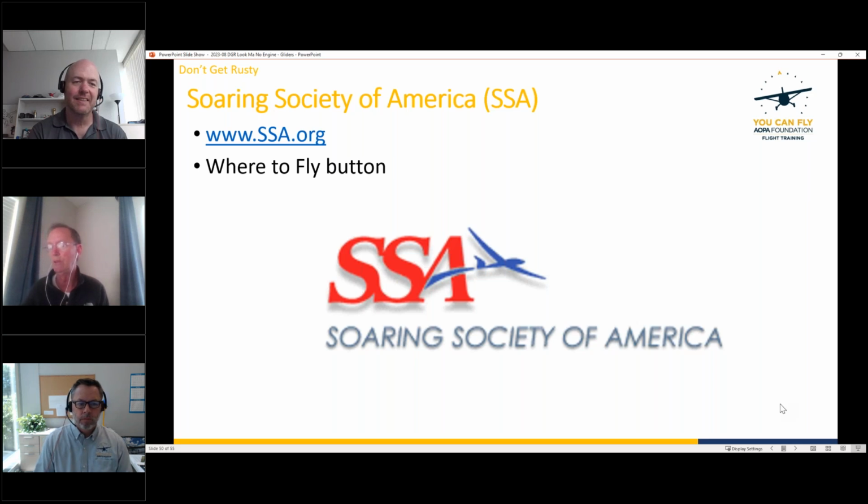So the local glider operation will contact air traffic control and say, we'd like to open the wave window during these times. Air traffic control will open that wave window, and then gliders are free to fly above 18,000 feet in that limited airspace. Air traffic control will route everything else that would normally go through that airspace around it so that it's not conflicting. Normally, you can't go above 18,000 feet because you need an instrument rating to be above 18,000 feet.